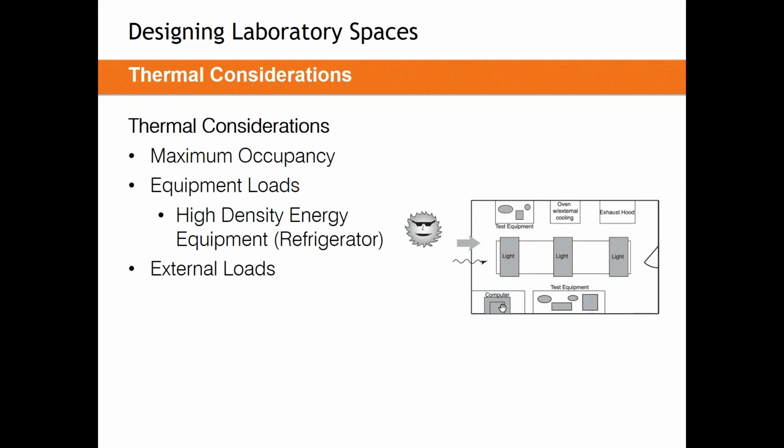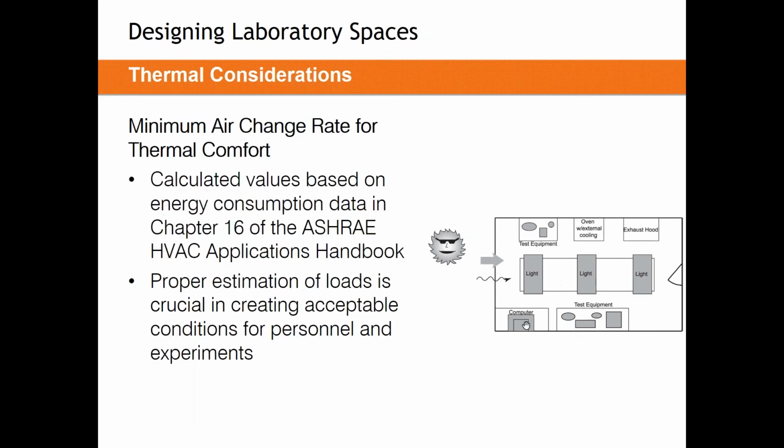Just like every other space in HVAC, we do have to concern ourselves with thermal loading. We do have to concern ourselves with occupancy, but most importantly here, we have to concern ourselves with equipment loads. Labs are a space where you might get extremely high density equipment. Notably, refrigerators are going to be one you have to deal with. They can be in the thousands of BTUs that you have to condition, and they might operate 24/7.